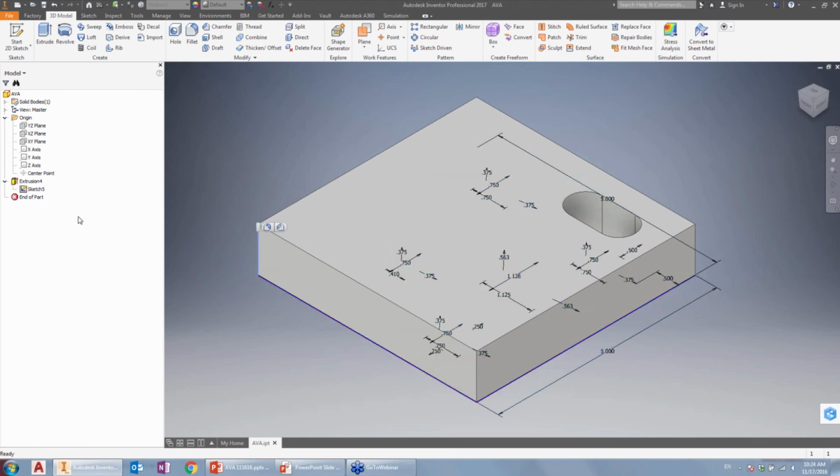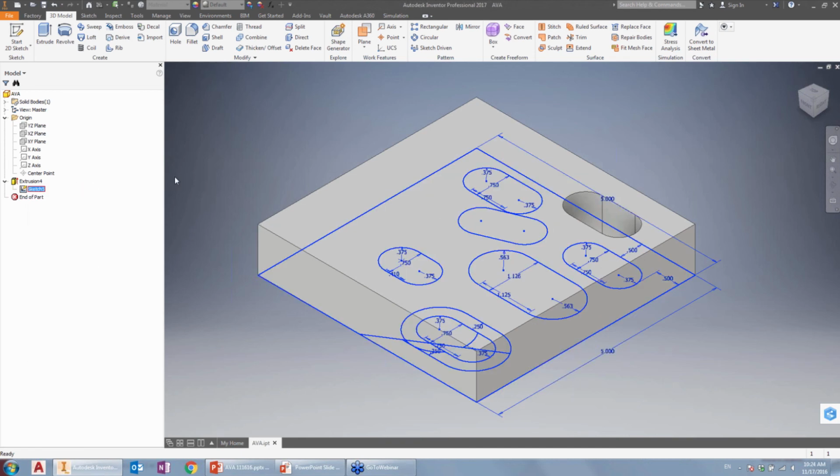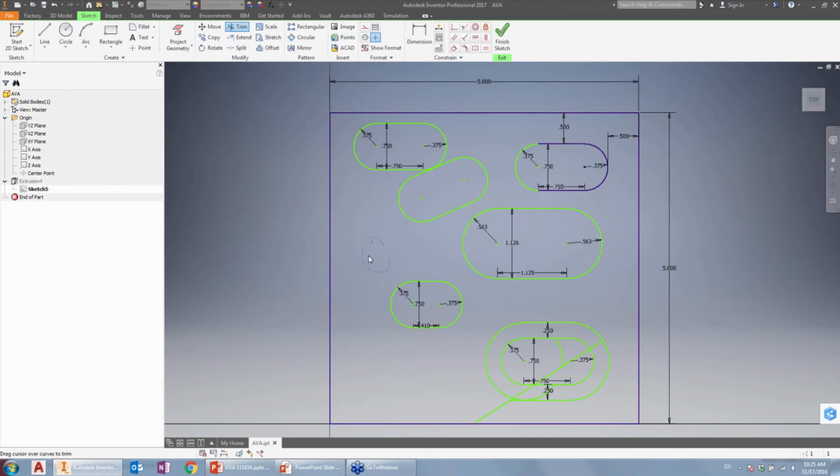Let's see. What's the name of that faint blue curvy line that you use to select items? Yeah, Ron, if you could clarify that. If you're talking about the line that Daniel's showing on the screen right now, that line is for dynamic trimming and dynamic extend. To get this to come up, you have to be in trim or extend. You click and then you just drag your mouse around. You hold the mouse down, and once you cross any line of geometry, it'll cut it or extend it depending on what tool you selected.